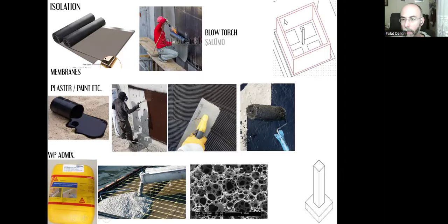However, here we will have lots of smooth surfaces and the application will not be that difficult because there are fewer, large surfaces. To apply these membranes with a blowtorch will be easier than applying it to a single strip footing. And if the shear walls crack somehow, we know that the paint or plaster will crack with the walls as well.